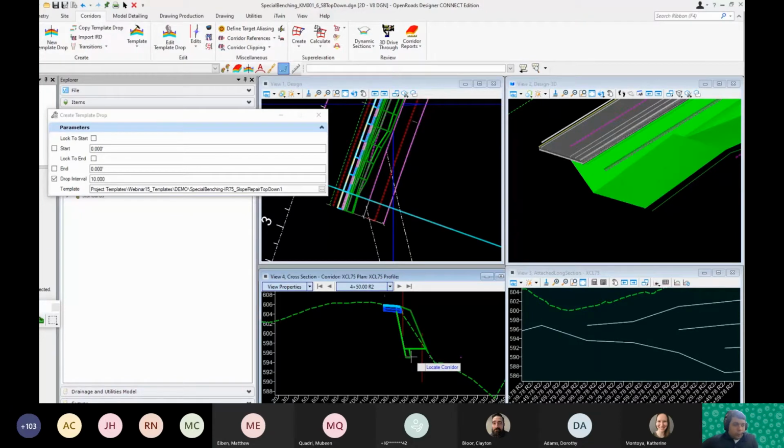So one way to do this is through the profile view, right? That bench elevation is just too low right there. If we had a profile telling it to match up with the elevation of our single bench, that would clean it up, right? So that's one way you could do it, is just have the profile tell this top bench to be right here. Then they're right on top of each other.